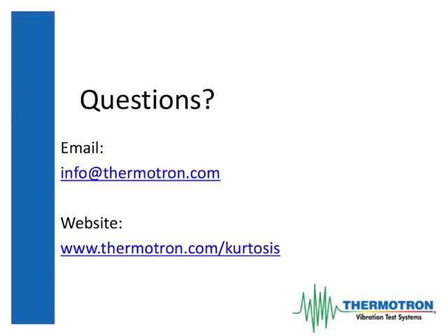I love to talk about it, but if your goal is to quickly test against something that has the same harshness as the real world, you should really just turn your normal Gaussian test up as high as it can go without going over the peak stress levels and just let it run. All right, well, we have time for a few more questions, so here's the next one.